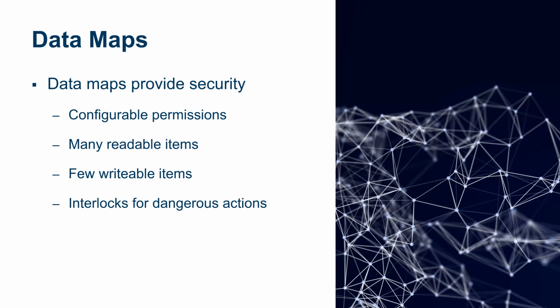They let you map items on the process to a specific integer value, a specific address in the protocol, right? So you might have an open breaker, a closed breaker, you might read a voltage, you have all these different things you can do. And data maps in the protocol are a thing that lets you control, from another device that's using DNP3, what can I ask this device for? I can ask for a voltage reading, and I'm allowed to read that with any permission, right?